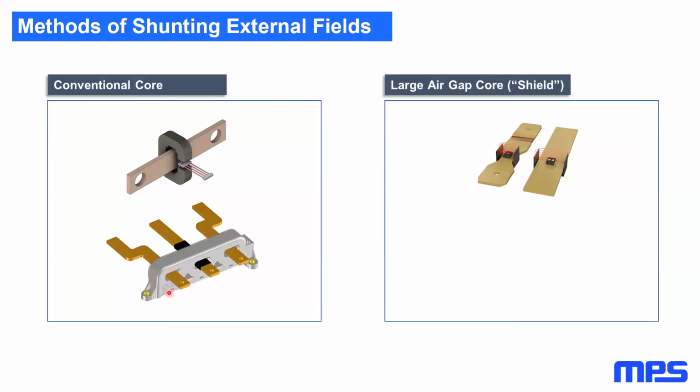In fact, you can even see the little LEM logo on there. In here, this is 3 phases, and each of these will have a closed core. And now if you have an external field, it will essentially shunt that external field through this super high permeability soft magnetic material. It's not perfect because there's this little C-cut in here, but it's pretty darn good.